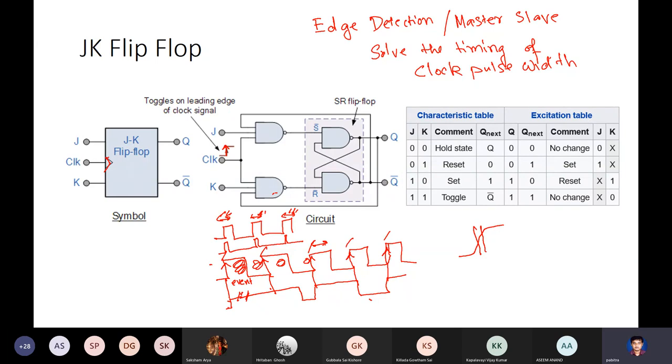So what actually is done in practice, and what I will do, is that I will take all these flip-flops, the JK flip-flop or the SR flip-flop or whatever, and their enabling input, earlier I was saying is on-off clock, now the enabling input is on only at this leading edge. This is the only period in which it is on. So if we look at the enable input, it's only this much.